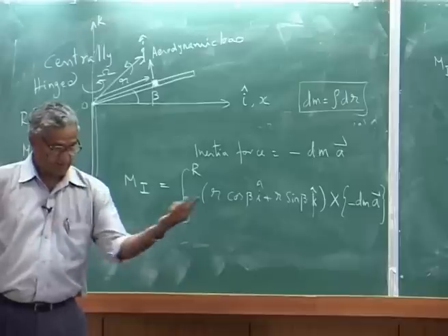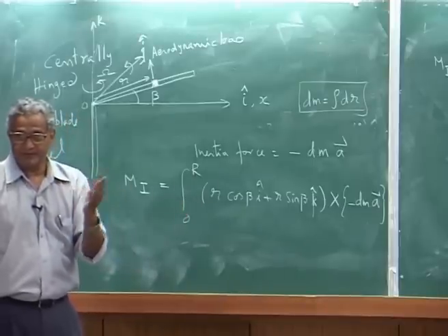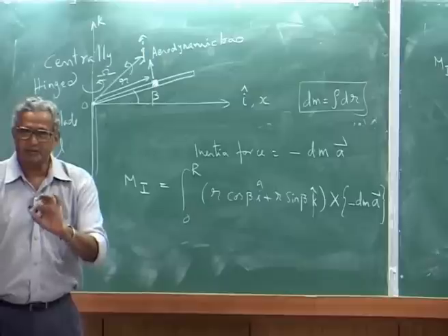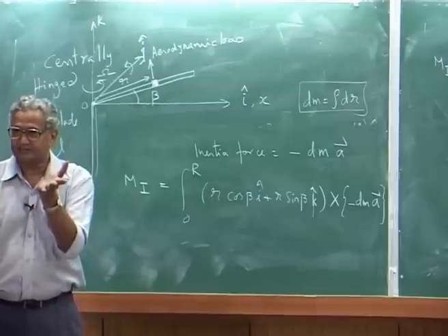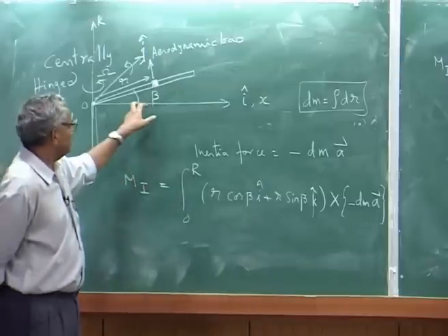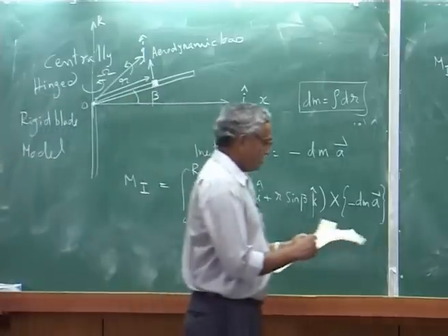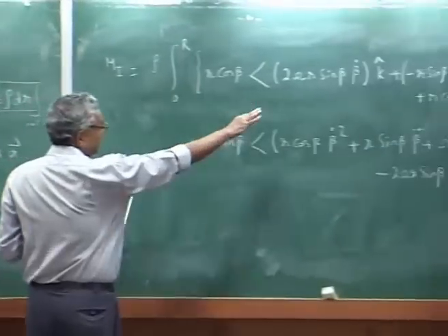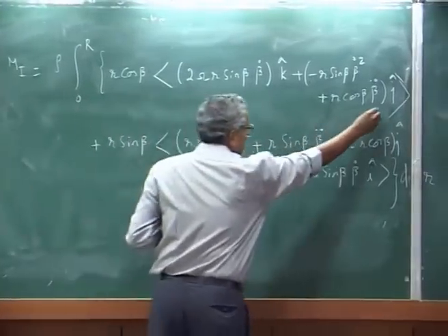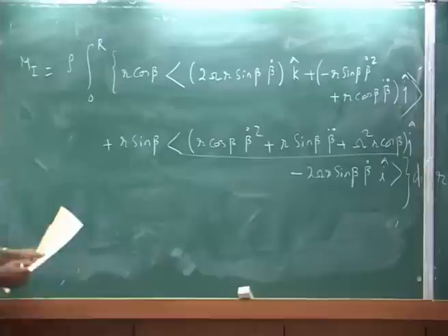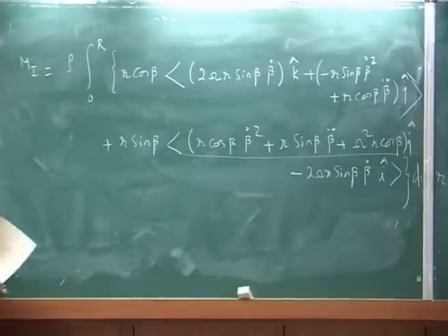Please note the j axis is also changing, it is not fixed. I am calculating the moment about the j axis, because that is the one that goes to flapping. So the j component has one term here and another term here. If you add both, that is about the j axis.